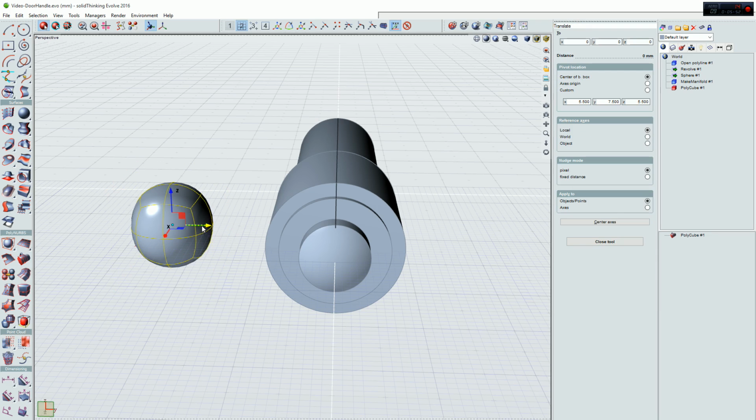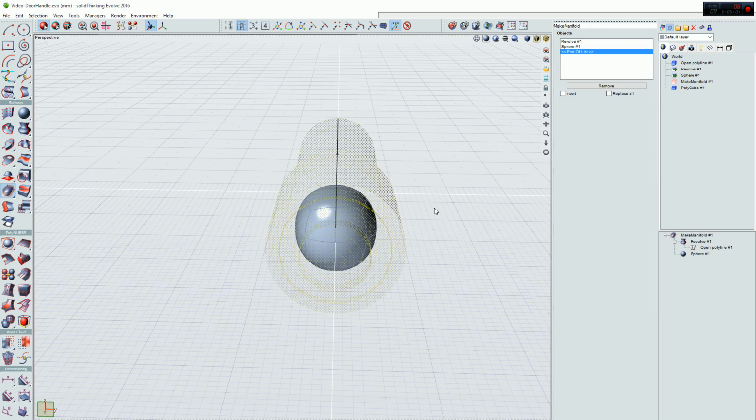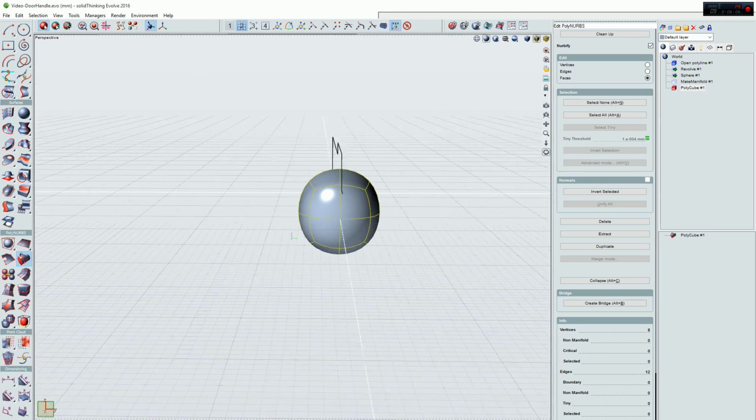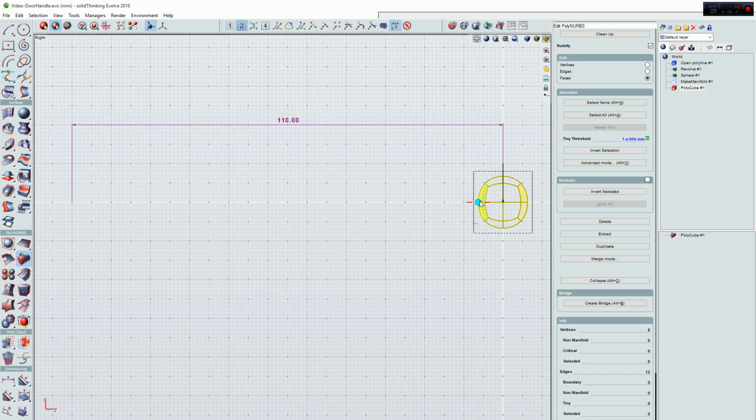And then we just move everything inside, like here. We will start from here. Now we don't need this for now, so we can hide it. Okay, and continue working on our handle. Now this is the starting part of the handle. We will start from there, and we will use a very nice feature of the polymesh editing, which is the extrusion. So we can just click this handle, click and drag to extrude the face, and we can start extruding it and creating our handle.